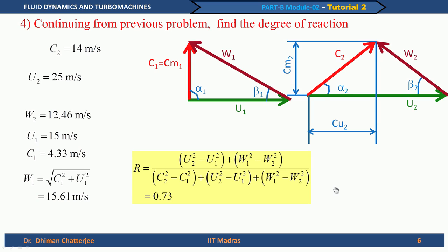So, these are some of the problems. While solving problems on pumps, turbines, or any turbomachine, please keep in mind that you should draw a neat picture of the velocity triangles and try to draw the angles. You do not have to make it exact, but try to make it look close.